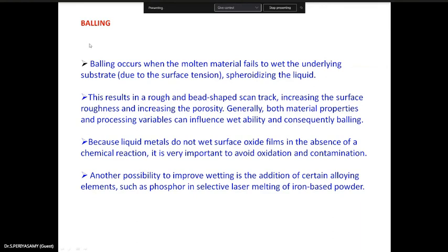As the hatch spacing is increased, lines of porosity and unmelted powder form. When the hatch spacing is increased, it leads to this porosity and unmelted powder. The hatch spacing at which parallel tracks fail to coalesce becomes the indicator of the limit of resolution, the limit of resolution of the particular system you are making, even a cellular structure or whatever it may be.